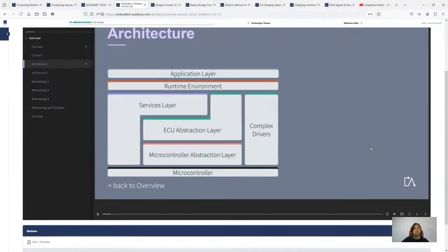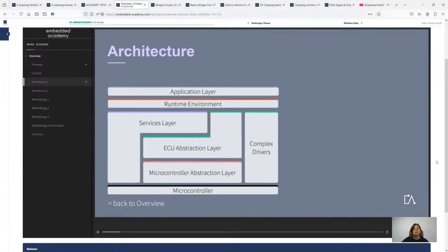The main concept of the standardized ECU software architecture is the separation of hardware-independent application software and hardware-oriented basic software by means of the software abstraction layer, runtime environment. The runtime environment includes the control of the data exchange between these layers. This forms the basis for a component-oriented, hardware-independent software structure on application level, with software components as individual units.